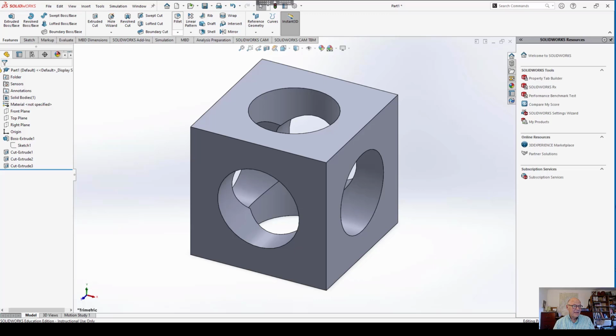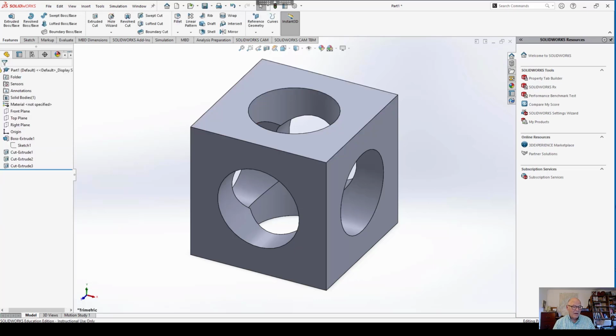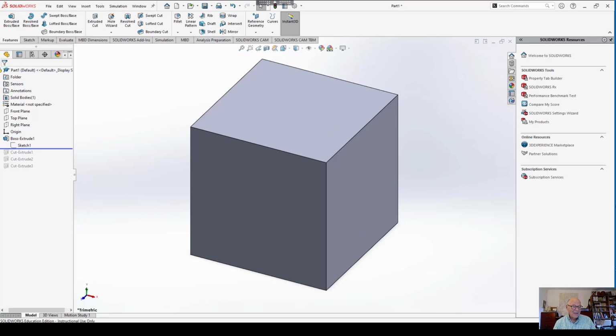So I can do a chamfer by going to the fillet tool under Features. There's a little arrow, and picking chamfer instead of fillet. Then I can pick every single edge. But that's going to take me a while to do. I can do it, but it's something I don't want to do. So I'm going to come back over here, and this is another really powerful element of 3D modeling with parametric modeling. If I move my cursor so it sits right on that edge, when the little fingers come out like that, left click and hold it and then drag it up, I can go ahead of what I've already done, and then while I'm up here I can insert another feature.